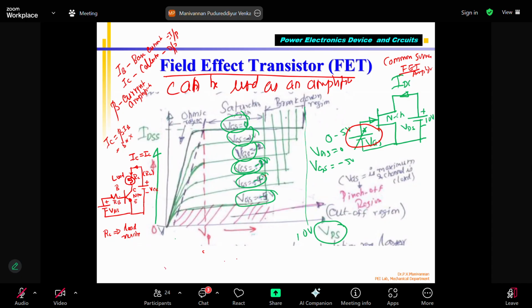So if I control the base current IB by controlling VB from 0 to 5 volts, with RB as 1000 ohms, IB will vary from 0 to 5 milliamps. If I say my beta equals 100, IC will be 0 to 500 milliamps. So we know that my transistor is amplifying my input current, which is the base current, 100 times. That's why we call it an amplifier.